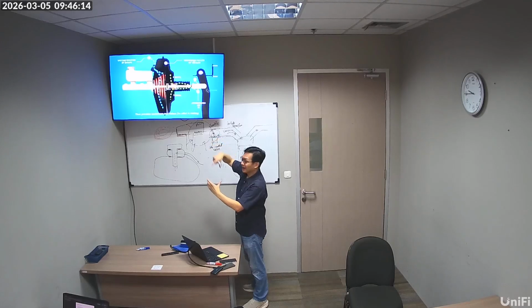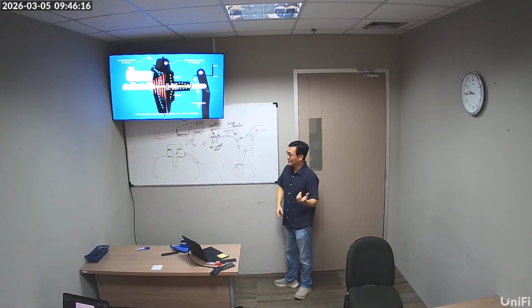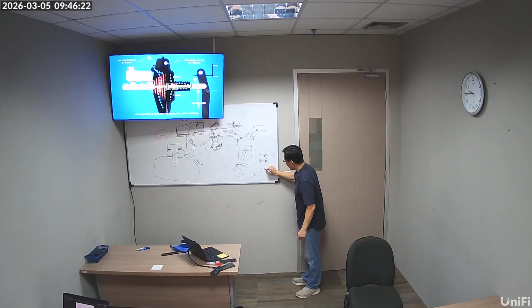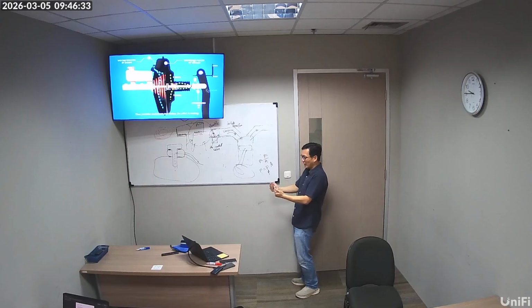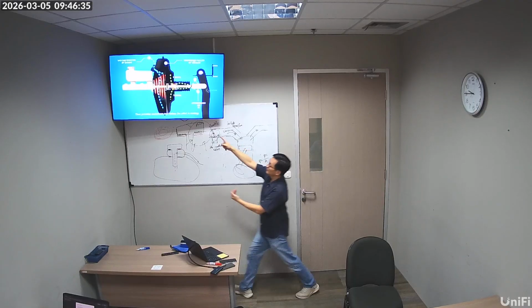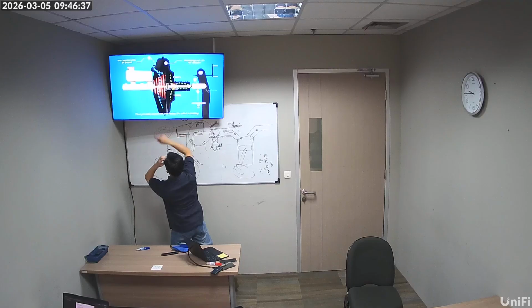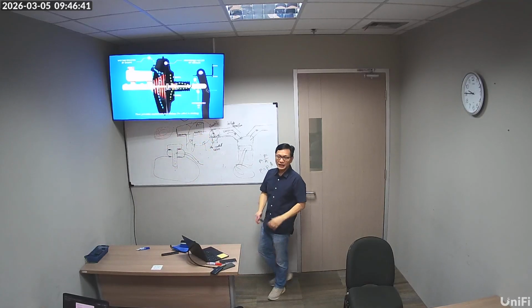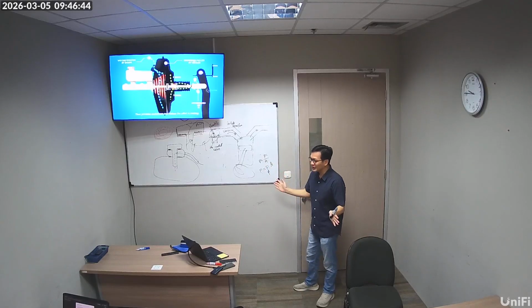Same principle as the hydraulics. Because pressure is force over area, and so force is pressure times area. The bigger the area, the bigger the force. So with the same vacuum, I can pull in a big force there. This thing pulls in with a big force. And so when you're pressing on the brake pedal, you are releasing the throttle, obviously.